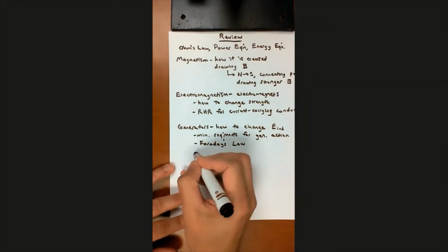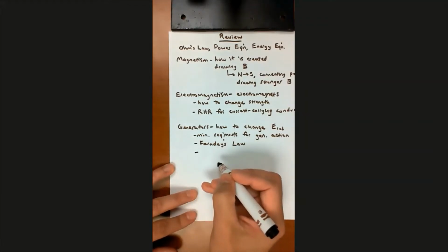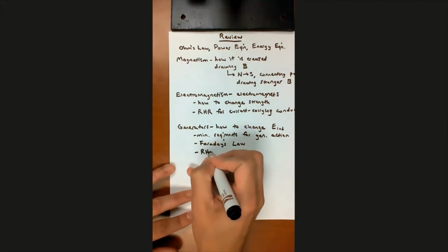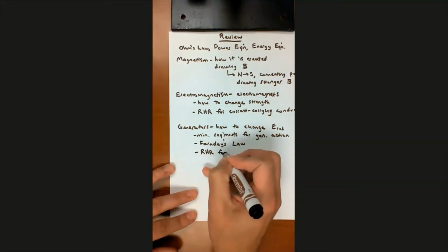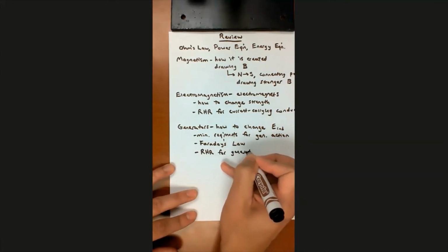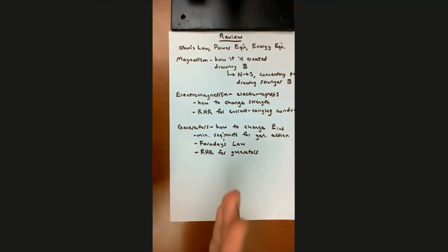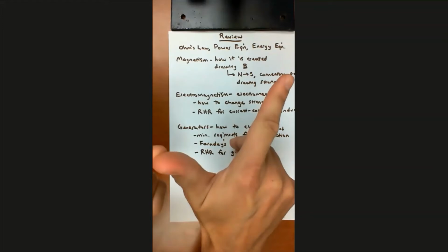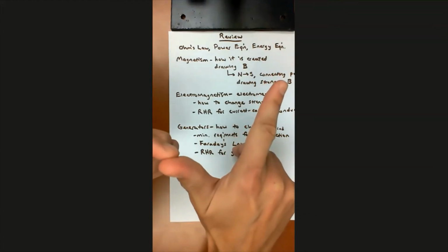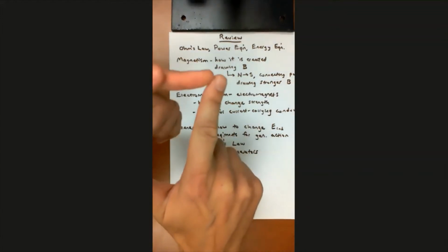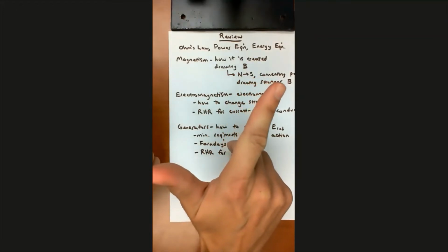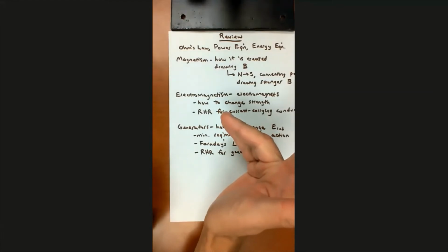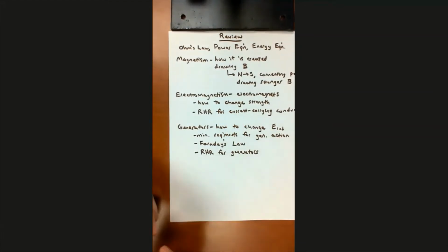And to find what the polarity of the induced voltage is, you can use the right-hand rule for generators. All right, so make sure you're comfortable using the right-hand rule, where the thumb gives you the direction of motion of the armature, the conductor, and the first finger is the direction of the field from north to south, and the second through fourth fingers give you the direction of the current that would flow as a result of the induced voltage.